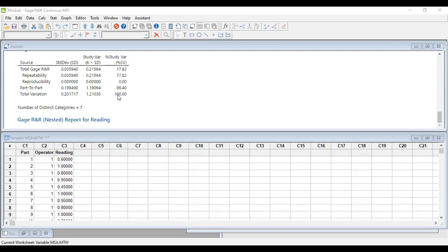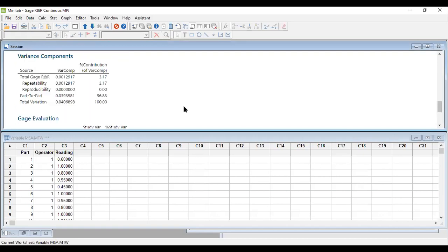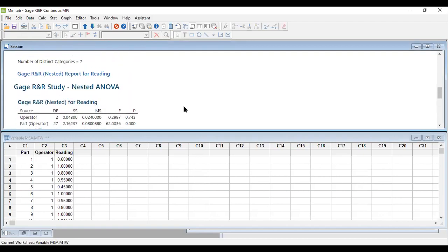So once you do this test, look at these three factors. One is study variation mainly. Tolerance is something we set. Contribution and distinct categories. If it comes into these three gauge, either in the yellow or the green zone, the gauge is acceptable. Or we'll have to change the data, or we have to look at reproducibility issue or gauge issue. Are you clear on any questions here?